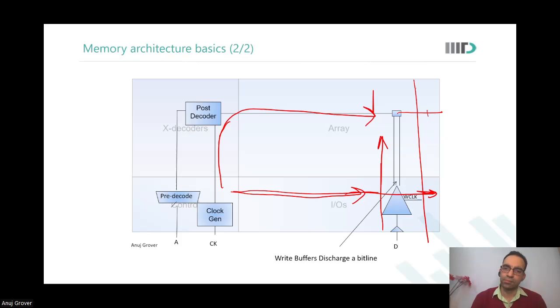Sir, the write signal. You say the write clock should arrive before the word line arrives. Because what we said was that before the word line arrives, my bitline and bitline bar should have been taken to 0 and 1 levels, whatever was the appropriate requirement. That is what we want. Yes, sir. Friends, why is it that only one or two people are speaking? I'm talking to the entire class. Please, I would be happy to have more participation.